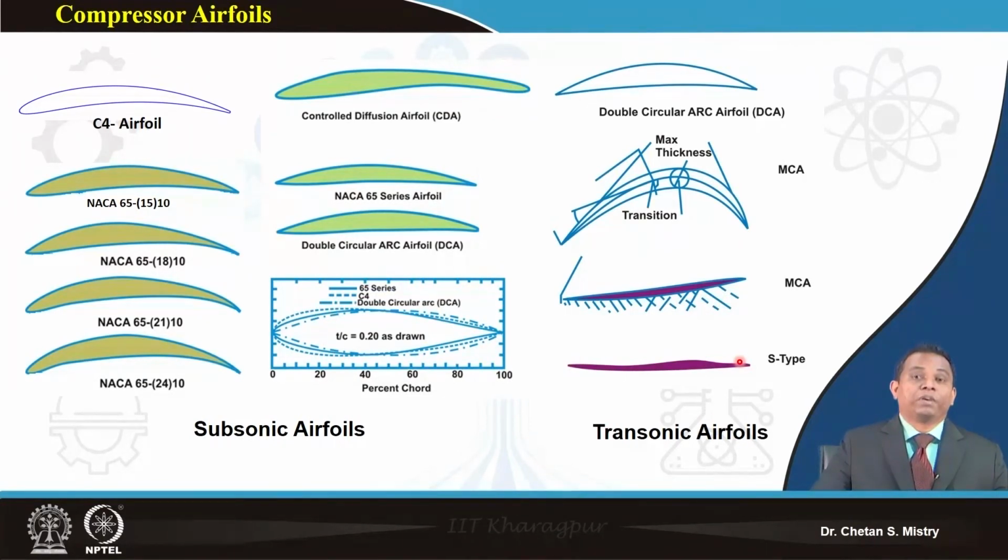Earlier people were talking about high bypass ratio engines and low bypass ratio engines, where we know the flow will go transonic near the tip region, where they used to use these transonic airfoils. Now, with the maturity of technology, the use of computational tools, more detailed understanding of flow physics and good experimental results, people are able to design the blades of the fan.